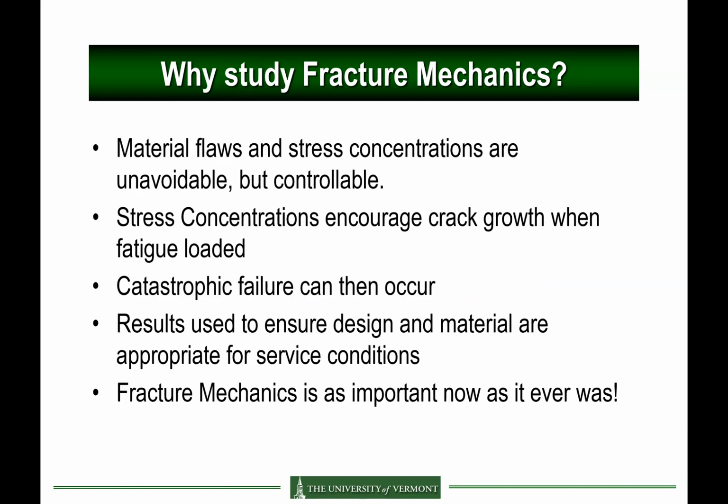So why study fracture mechanics? Materials have flaws, structures have stress concentrations, and this cannot be avoided, but they can be controlled by design. Stress concentration encourages crack growth when the structure is subjected to fatigue loading. Then it follows catastrophic failure, usually after the crack has propagated to a certain length by fatigue.